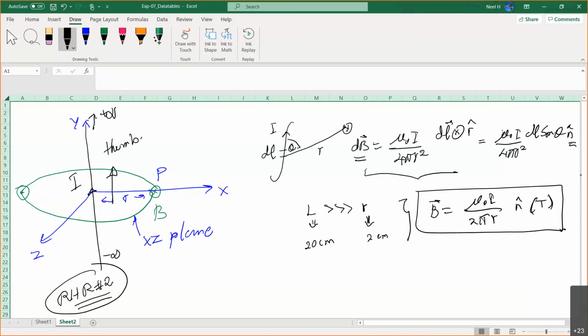There are two parts to the lab. In the first part, we will take a look at how this formula works, technically validating that formula. If we can validate it by measuring the magnetic field around the current wire, then we can validate the Biot-Savart law, right? So this law can also be validated. That's the plan. To do that, we can measure the current directly. We can measure the radial distance directly, right? And the magnetic field we can also measure directly by using the magnetic field sensor.